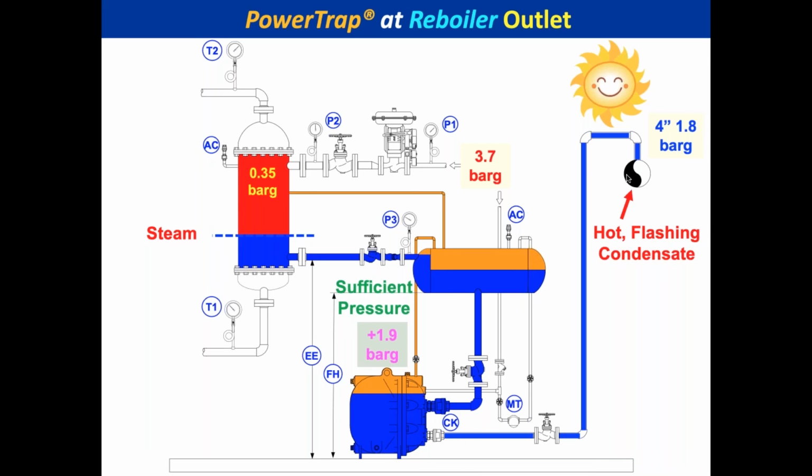And when you come into the top, you're immediately mixing the colder condensate with the flash steam. You're going to get a collapse. You put it into the side at 90 degrees, you're going to get a bullhead. You're going to get a swell of condensate. You're going to get a collapse. So I'd put it in there at a 45 degree angle from the side and see if that worked.